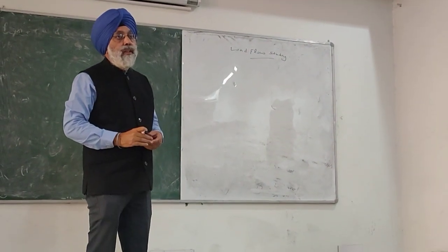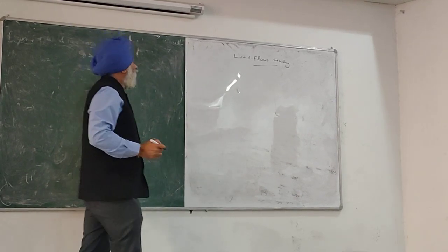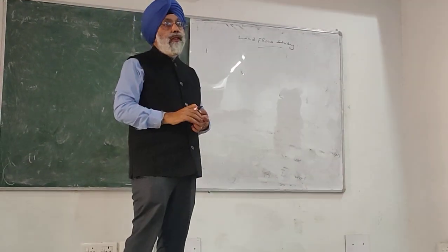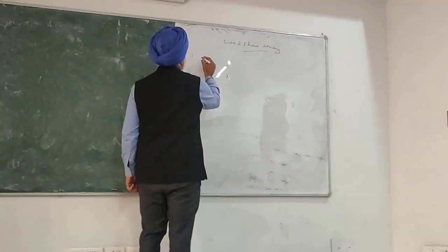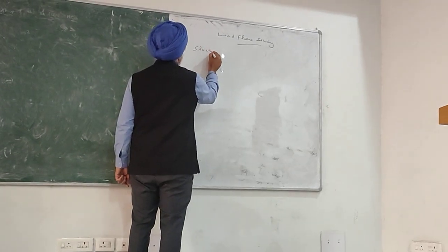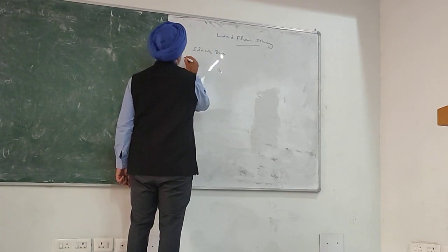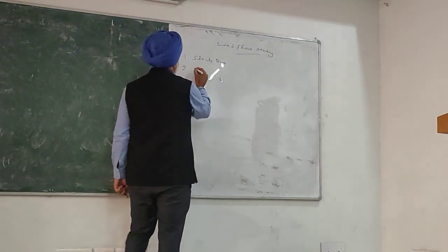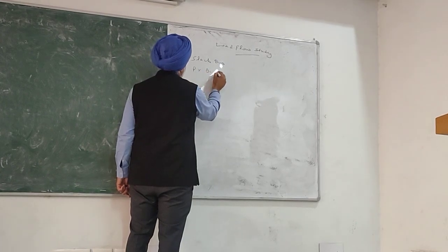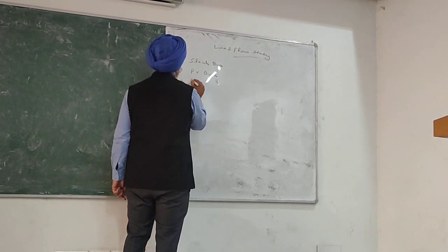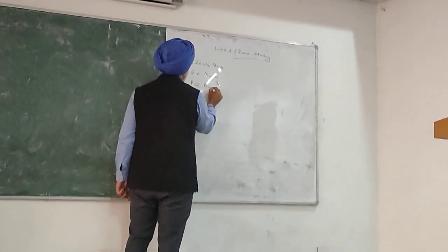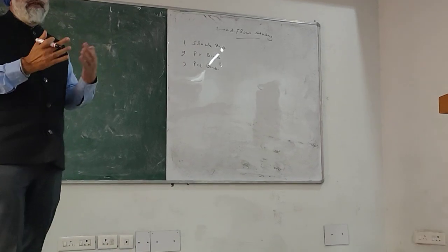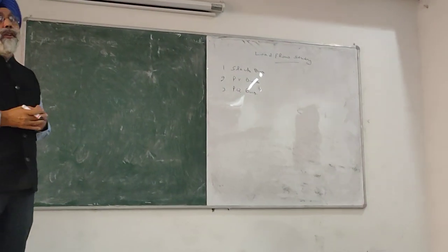In the load flow study, we studied that there are different types of buses. We consider the different types of buses in the system. First type of bus is slack bus. Second type of the buses is PV bus, and third is PQ bus. In addition to these buses, we have the voltage controlled bus also, if we have some tap changing arrangement regarding the change of the voltage.